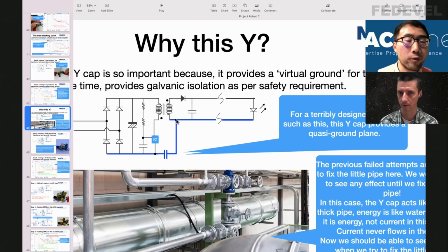That's the RF voltage. If you put a capacitor between these 2 points, the capacitor works with frequency: when your frequency increases, the impedance drops. So it's making sure that the potential of this point and this point, from the RF point of view, is more or less the same. So you don't have a voltage noise source between the two sides, meaning primary side and secondary side, and you don't drive any emissions up.